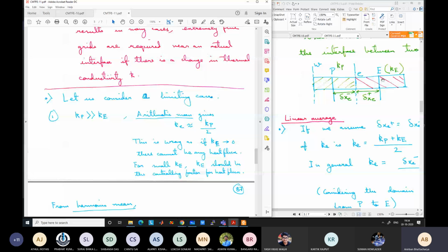If the handle is of very poor thermal conductivity, I will still feel safe that the handle is not getting heated. Although copper has much higher thermal conductivity as compared to aluminum, copper or aluminum is not the governing factor here. The insulating material is the governing factor, and heat flux is almost equal to zero.